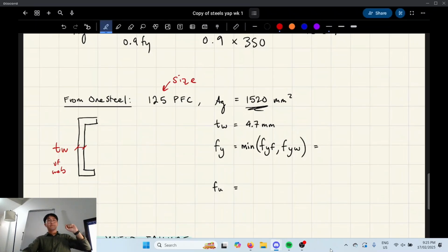Because if the gross area is fixed, then it has to scale, it has to ratio with the web and the flange. But we have the number for the entire thing, so why do we care specifically about tw here? Because the web makes it skinny and it's going to collapse. In what type of failure? This one. That's compression though.